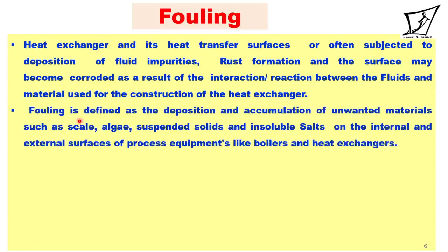So fouling is defined as the deposition and accumulation of unwanted materials such as scale, algae, suspended solids, rust, and insoluble salts on the internal and external surfaces of process equipment like boilers and heat exchangers.